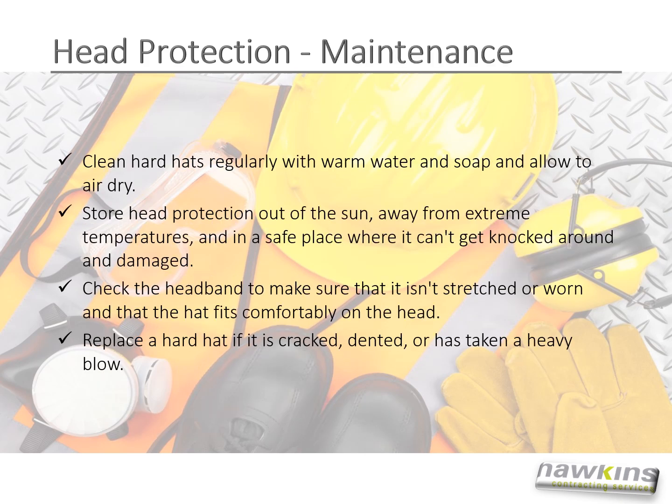Do not neglect maintaining your hard hat. Clean hard hats regularly with warm water and soap and allow them to air dry. Store head protection out of the sun, away from extreme temperatures, in a safe place where it can't get knocked around and damaged. Check the headband to make sure that it isn't stretched or worn and that the hat fits comfortably on the head. And replace a hard hat if it is cracked, dented, or has taken a heavy blow.